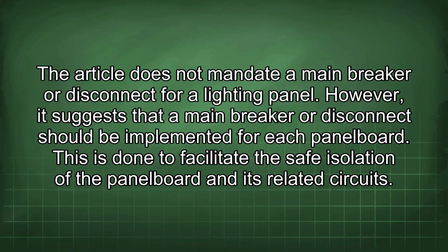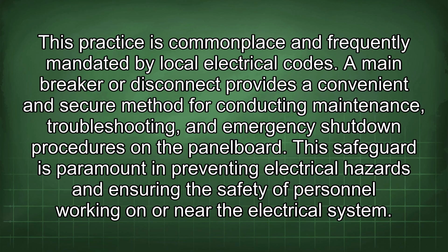The article does not mandate a main breaker or disconnect for a lighting panel. However, it suggests that a main breaker or disconnect should be implemented for each panel board. This is done to facilitate the safe isolation of the panel board and its related circuits. This practice is commonplace and frequently mandated by local electrical codes.